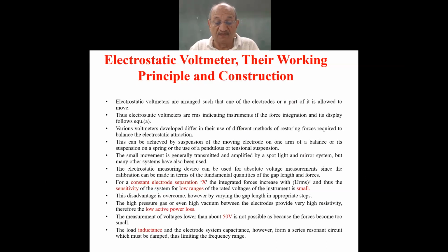Thus, electrostatic voltmeters are RMS indicating, as from the theoretical derivation, the mean value has been calculated. The force would depend upon the mean magnitude of the voltage. It is an RMS indicating instrument if the force integration and its display follows the equation we have seen.